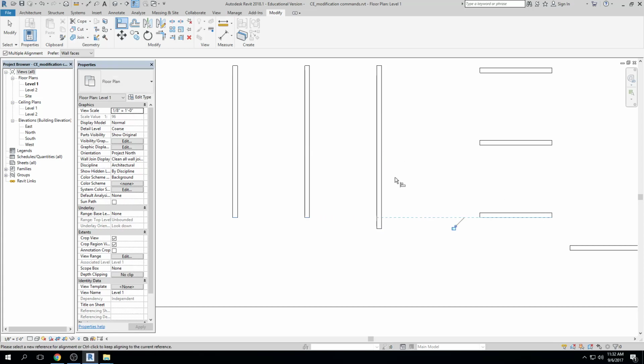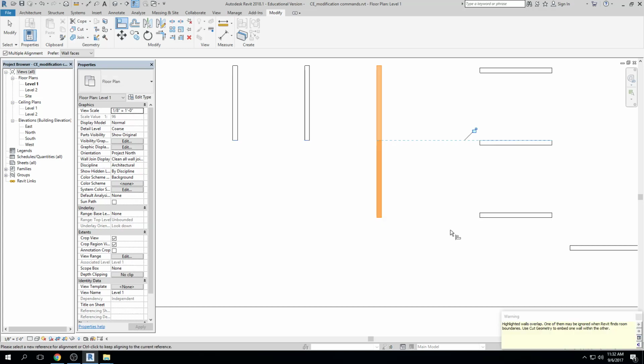So you're noticing a couple of things here, right? That in AutoCAD, that's an extend, right? So align will allow you to take one object and line it up with another, right, in kind of the same plane. But it will also allow you to take an object and extend it and align it with a point somewhere else, right? And that occurs in an extend operation and also in a trim sort of operation. So I can type AL, I can click up here, click, and these will trim back, click. Oh, that one, I knew there was something there, but it went back up. So this one extended up to that, and because these were touching, this one came down to that alignment there, right?